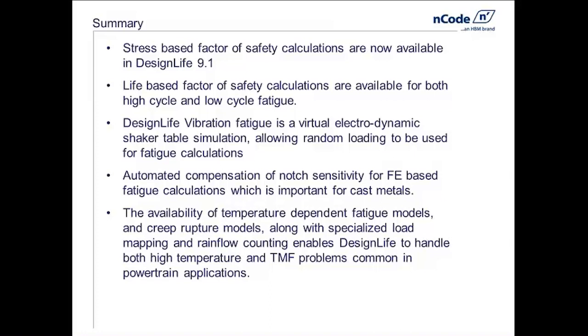And then finally, we looked at the availability of temperature-dependent fatigue models and creep models inside of DesignLife, along with the hybrid load provider and the enhanced rainflow counting to allow us to do both high temperature fatigue calculations as well as full TMF, thermo-mechanical fatigue problems.